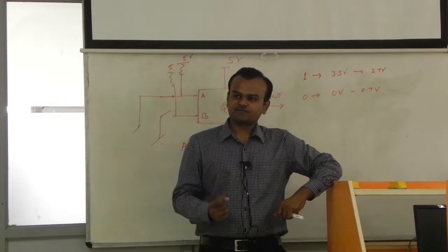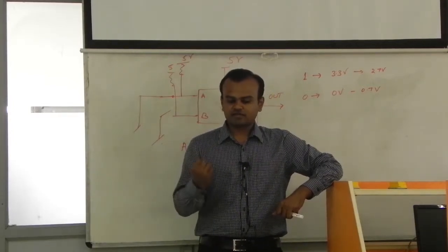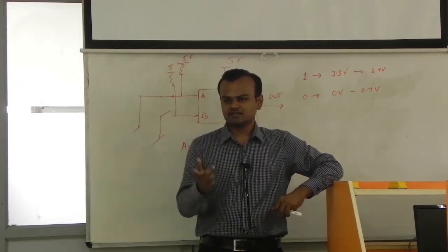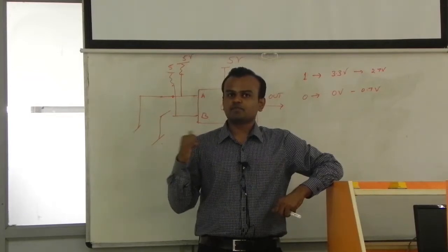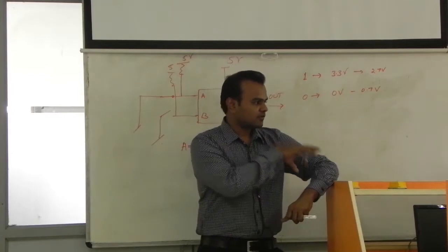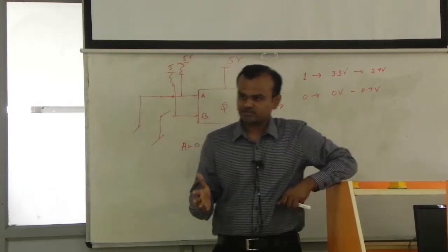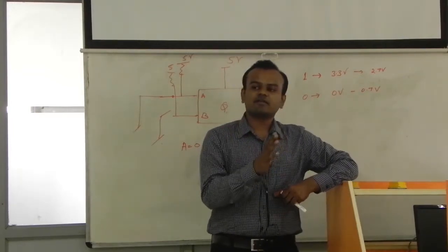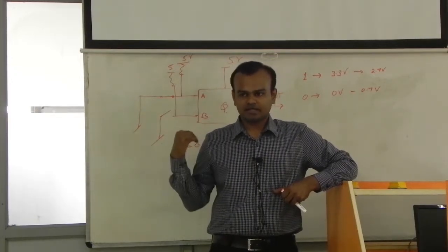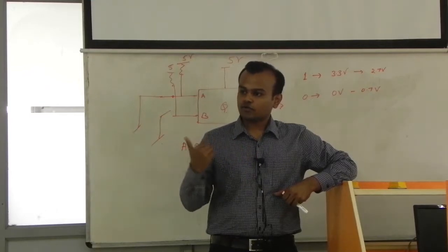Now in addition to this, there are other clocks available on the system. For example, this system doesn't have an ACLK, which is something present in some systems. This system has a PCLK for a peripheral clock. So all the peripherals on board, like GPIO, UART, serial interfaces, can be run at a different frequency than the main core. Even if your main core is running at 12 megahertz, your peripheral clock could run at 48 megahertz. You could program it to do that.